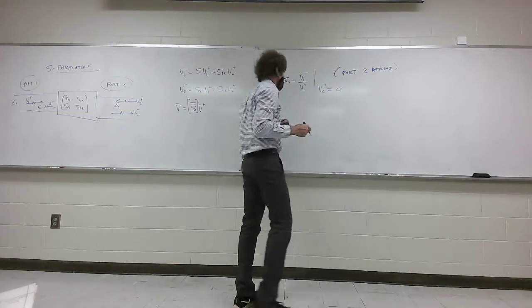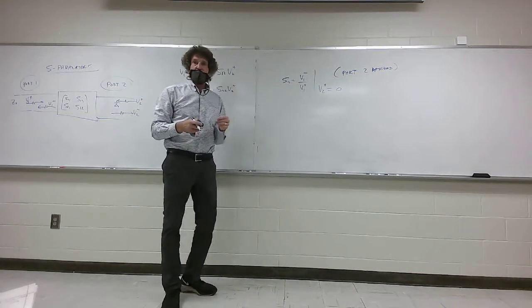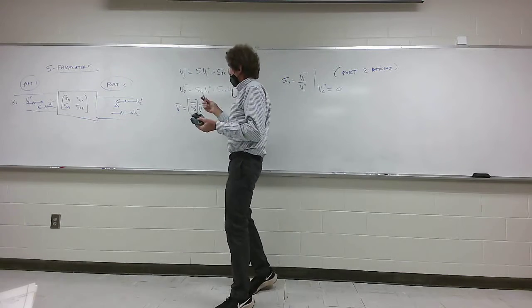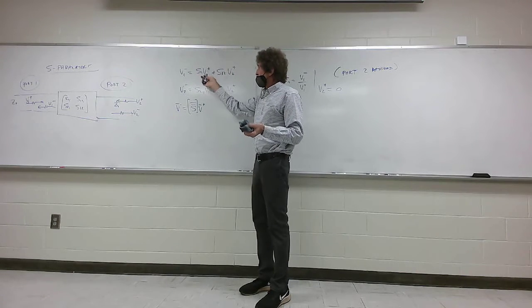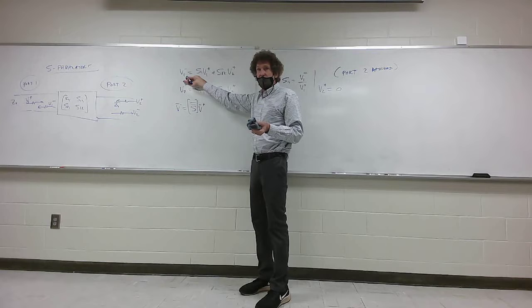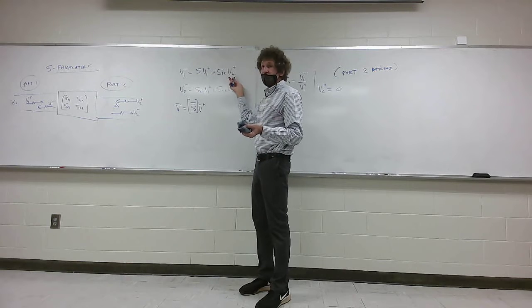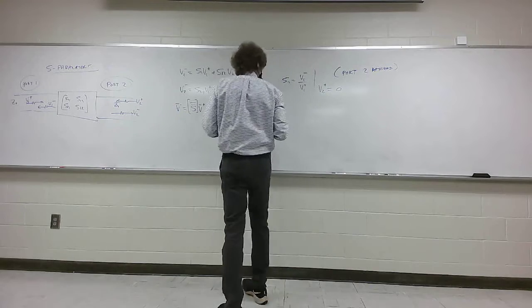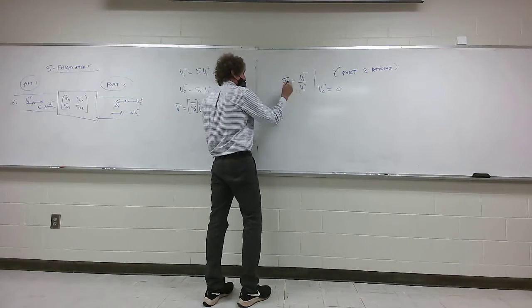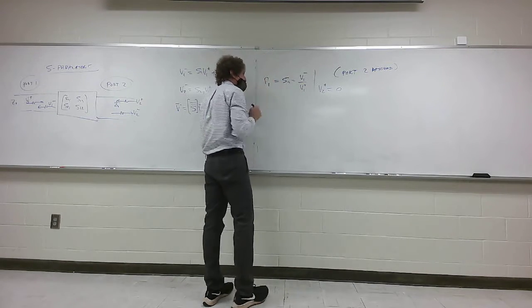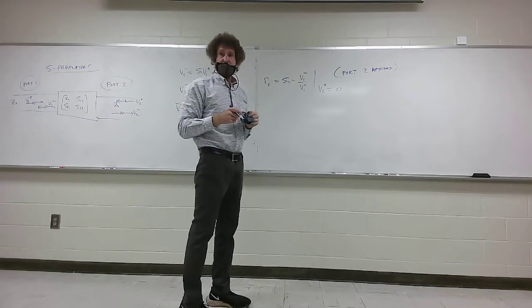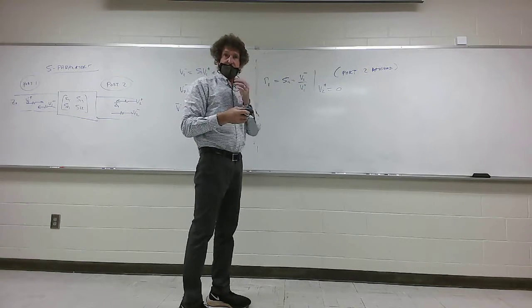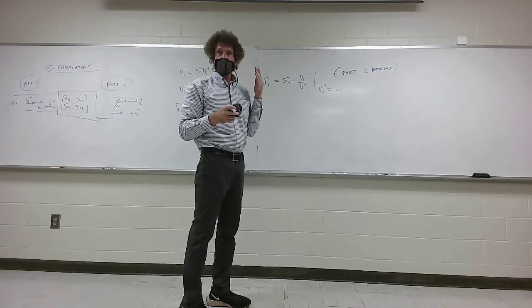All right? So, that's S11. And if you look, it makes sense. If I divide by V1 plus, right? And I assume V2 is 0, it is S11. Y'all follow me? This is just the reflection coefficient, by the way, when that's the case. That's the reflection coefficient of port 1 if it is matched. Do y'all follow me on this? Now, if it's not matched, it's not, but almost always it is.